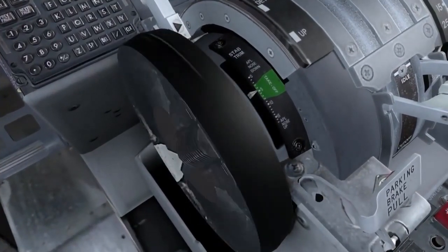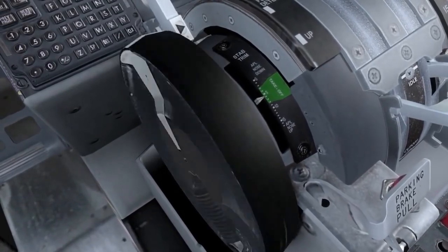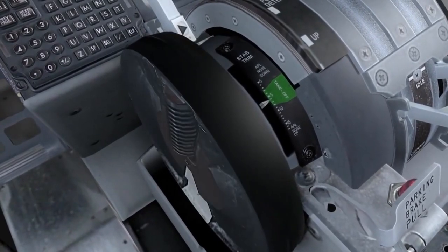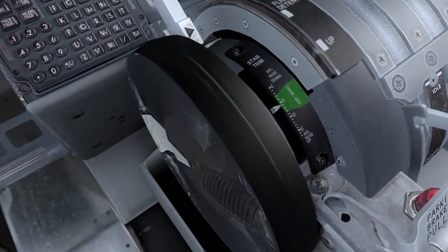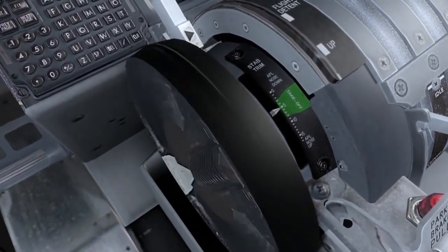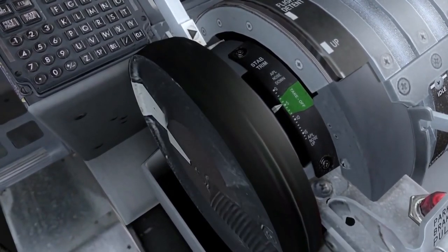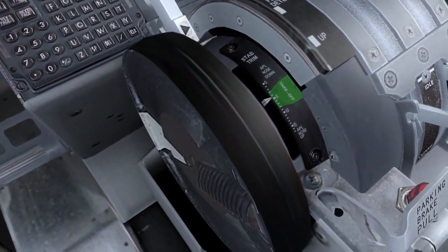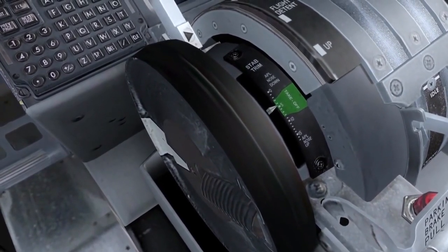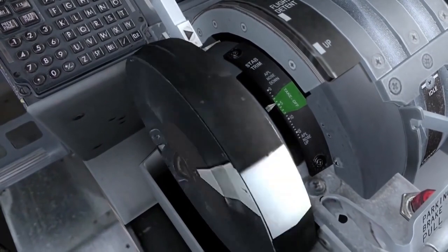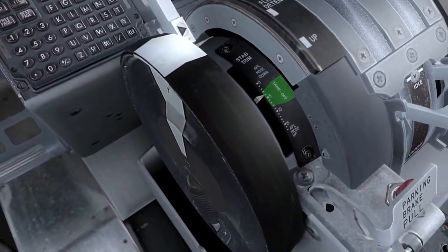During manual operation, the pilots use stabilizer trim wheels that are linked to a mechanism with a jack screw. When the jack screw moves, the horizontal stabilizer moves. It's good to know that under normal conditions, the stabilizer trim is the only control surface on the 737 NG that's completely independent from the need of hydraulic power. This also means that under certain flight conditions, the effort required to manually operate the stabilizer trim may be higher.